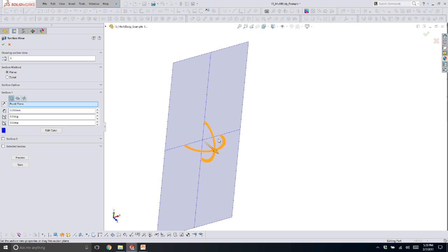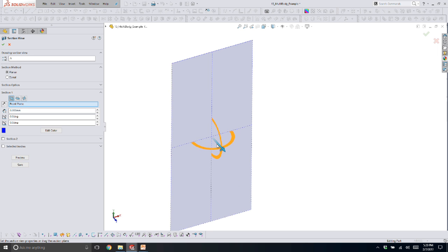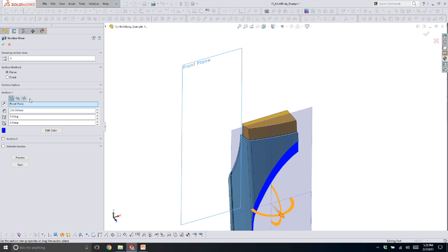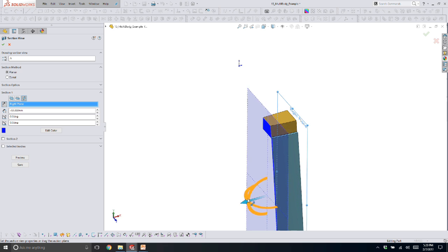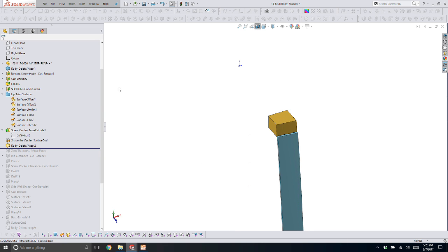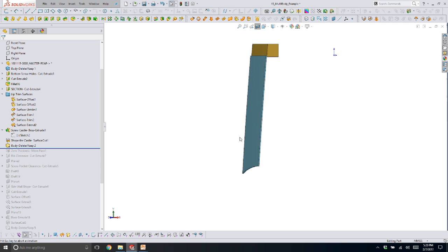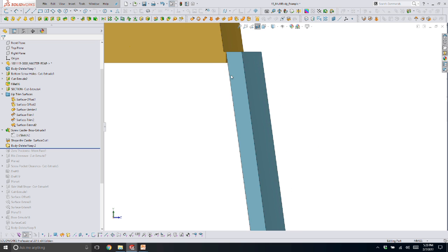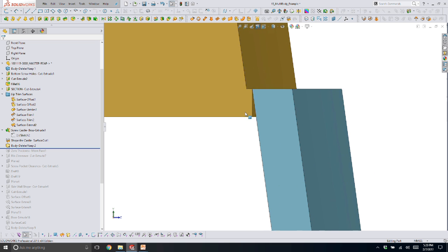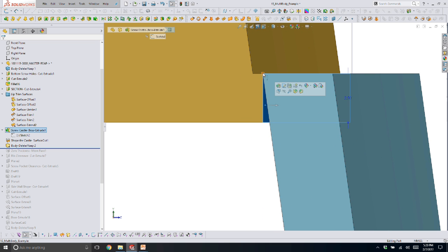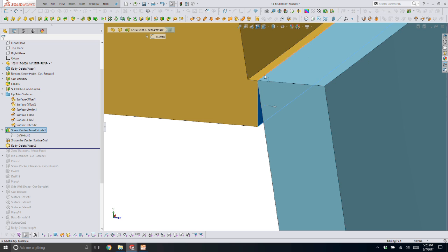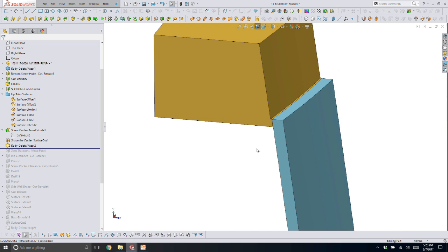One thing to be aware of is when we're mixing shapes created with surfaces, especially on the outside of a part, and we're now moving into the solid features. Solid features, especially extrudes, are always perpendicular to each other unless we've set a direction vector or the like. And because this is a nice arced crown surface, when we pick this inside edge, what do we get here? This is zero thickness geometry because we're zero thickness all the way through this edge. So when I went to combine, it would give me an error.